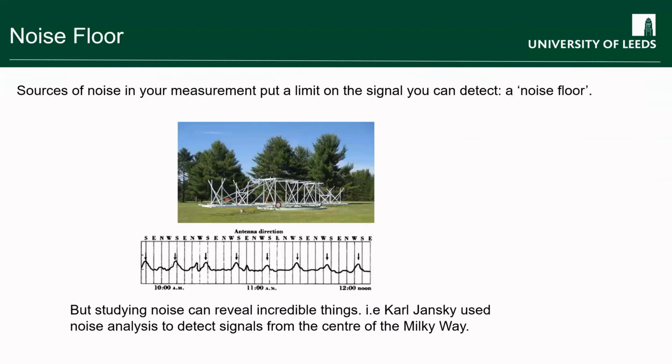So putting it all together, what you end up with when you're doing an experiment, and okay, we've been talking about a radio experiment, but the thing you've got to appreciate is that a radio is deliberately trying to pick up electromagnetic radiation from the environment, but actually any sensitive electronic measurement is going to have a certain amount of pickup of signals from electromagnetic radiation around in the environment. So you might be deliberately trying to tune into radio, or you might not be, but you're always going to end up having some level of interference.